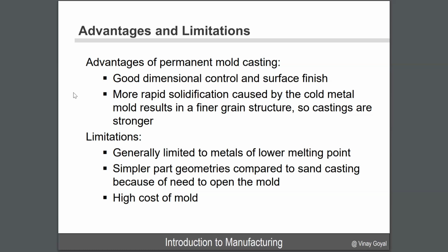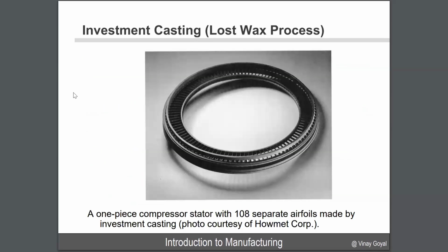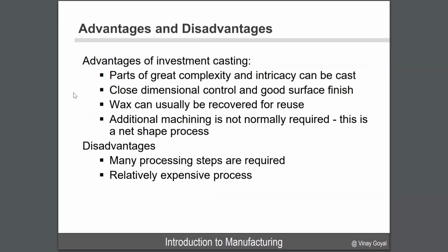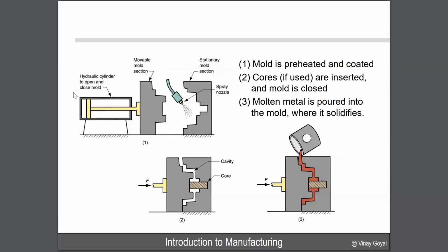And what I'm trying to do is push you to compare these, not in your head only, but looking at, okay, I want to make this part. I want to make this part. Without seeing what the title of this chart is, you can quickly say, I want to make this. I think investment casting will be better because I can get dimensional control that's very nice. I can get great complexity. Are you following what I'm trying to say here? Yeah. So very important that we can do that.